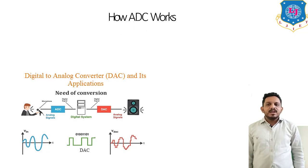Let's see the working of the ADC. As I said, here is one example application of the ADC and DAC both. One person is speaking to the microphone. It should be given to the ADC, that is analog to digital converter. Then once this is converted into digital, it is given to the digital system. This digital system will do the increment or amplification process. So the signal will be amplified. And this is DAC. So again, the digital signal is converted into the analog signal. And this analog signal is now given to the output device, that is the speaker. So even if this person speaks at a very low volume, we get the output at a very high volume.